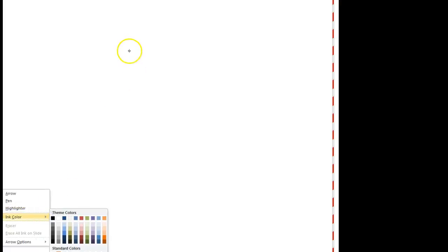So this is what we need to do. This is the current file. Let's say my index register, what do you want to put in the index register? 5. Okay, so we'll put 5 in there. So somehow I set S24 to equal 5. So my instruction is B3, colon, and then what does it say? 0. This right here is the offset. So my address would be B3:5.